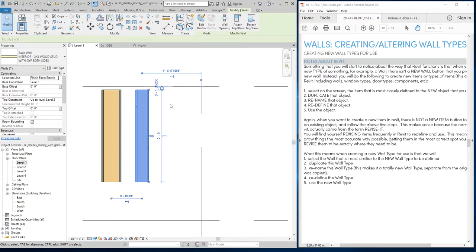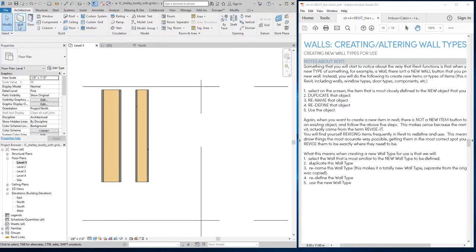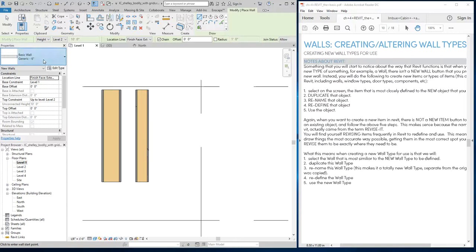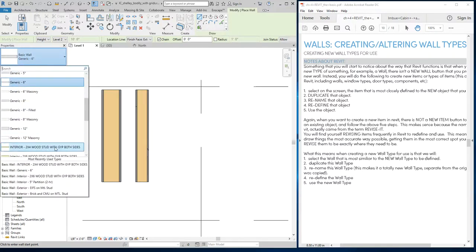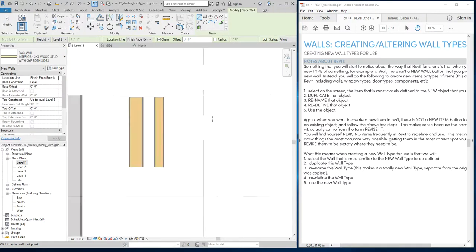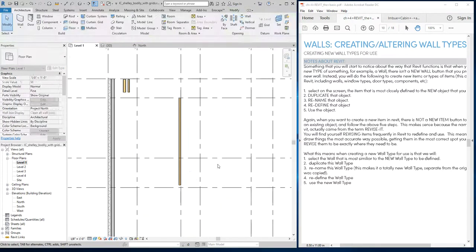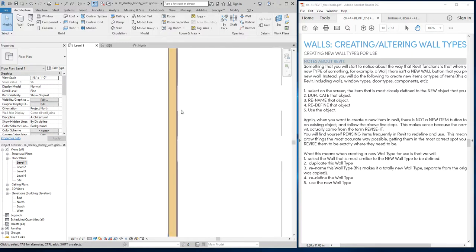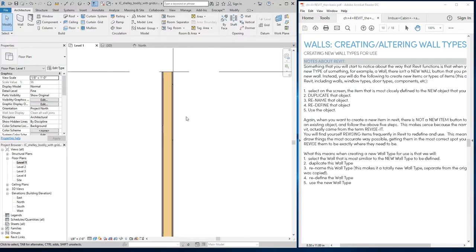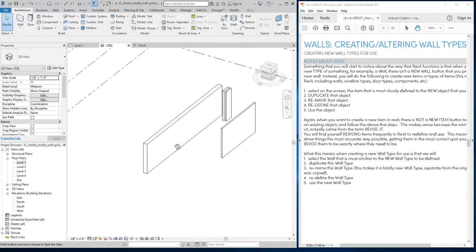Now, these wall types are available for me to use. So I click on Wall, and I drop down and I can see 2x4 wood stud with gypsum on both sides. Great, right? So now for your assignment for this project, instead of using just a generic wall with no definition, you're going to be using an interior wall, okay? And that tells us a lot. It tells us how many linear feet of wood stud we need and how much area of gypsum board we need for the project, right? So there's a lot of information that's conveyed.